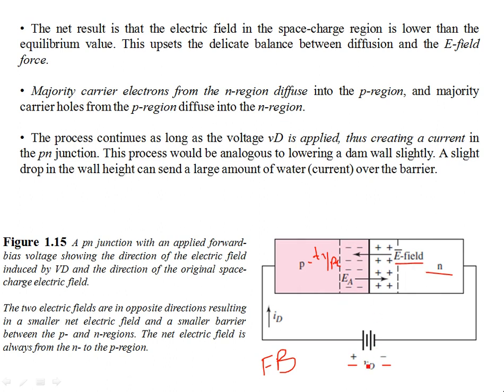The E field, due to the applied external bias VD, tends to decrease the overall field which is directed from N to P type region. Because you see what's happening over here is that in absence of bias, when there is no VD, it's open circuit. You have a barrier potential due to the uncovering of immobile charged ions on both sides, and they try to halt the diffusion process of holes from P region to N region and electrons from N region to P region, right? And an equilibrium is established, so there is no transfer of charges.